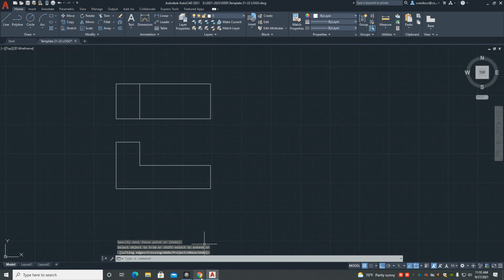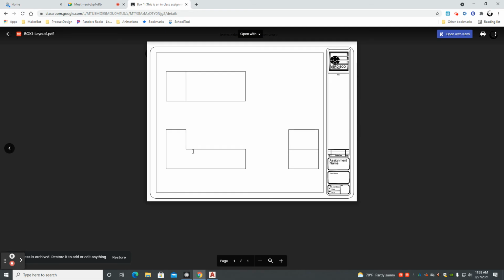All right, look at this. We already have 2 views done. We have this view and this view. So now we need to build this view. So we can draw lines straight across and have our guidelines give us our top, middle, and bottom lines automatically, no measuring. But we could also take this 3-inch line, bounce it off a corner line, a 45-degree line, which is called a miter line, and bounce the measurement down here.